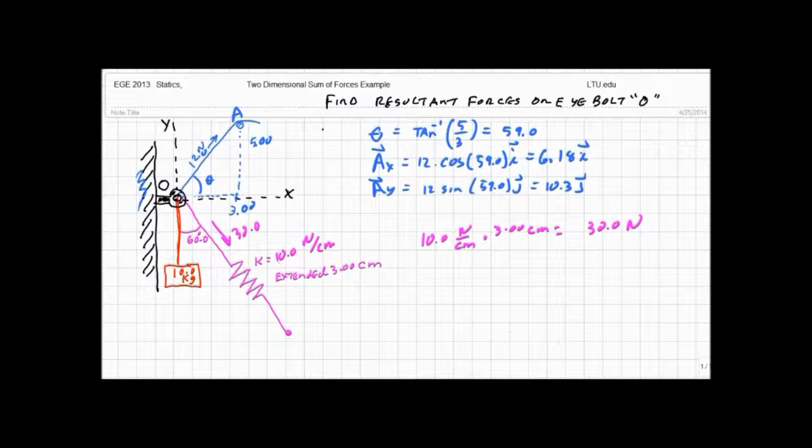Okay? And I have this at an angle of 60 degrees here from the vertical. Let me see where I've drawn it. Now, this is going to get a little bit messy. I can't just say that my A X is 30 times the cosine of 60 degrees, because the cosine of 60 degrees is really in that direction, right? So what I really want is the force in this direction for my X component. So that's actually 30 times the sine of the 60 degrees.